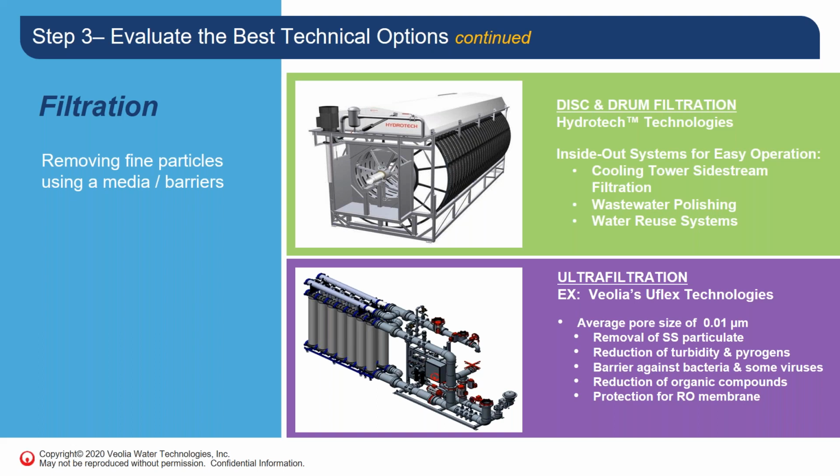It's great for putting upstream of further membrane systems such as ROs because you're protecting those membranes from fouling and from scaling through the particles that are removed in the ultrafiltration unit itself.